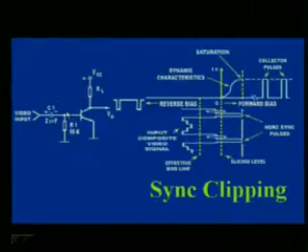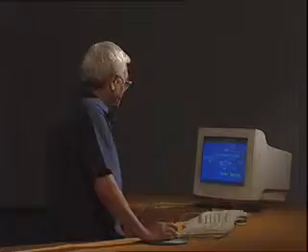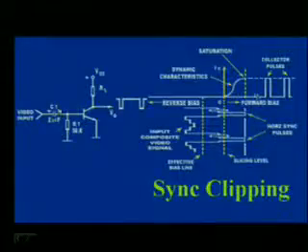They are for the biasing purpose of the base of this transistor. Here in this figure, C1 is of the value of 2 microfarad and R1 is of 56 kilo ohm.